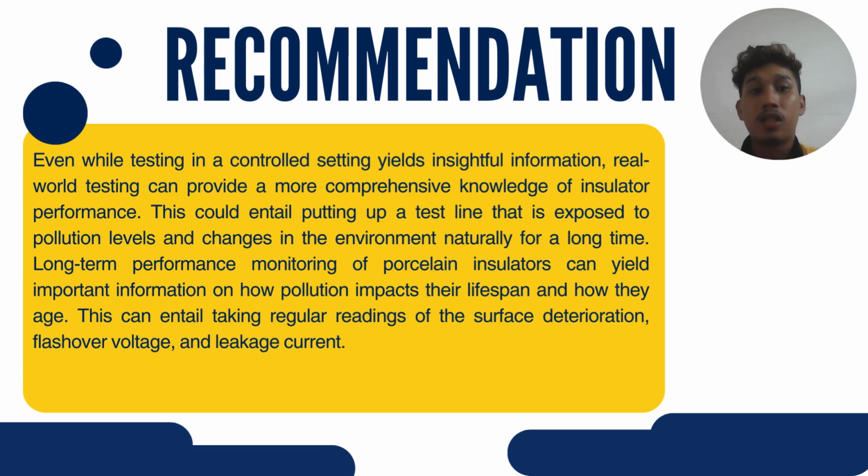Okay, for recommendations and for our future work, while testing in a controlled setting yields insightful information, real-world testing can provide a more comprehensive knowledge of insulator performance. This could entail putting up a test line that is exposed to pollution levels and changes in the environment naturally for a long time. Long-term performance monitoring of porcelain insulators can yield important information on how pollution impacts their lifespan and how they age. This can entail taking regular readings of the surface deterioration, flashover voltage, and leakage current.